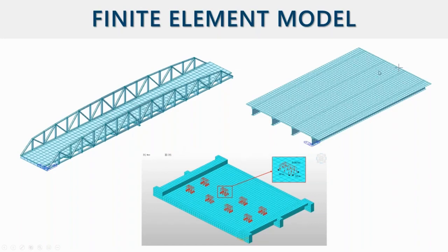This is the approach slab span with four steel beams, and this one is the approach slab span. You can notice that on the side they have these raised sidewalks, and this actually adds quite some stiffness. So we have to model this sidewalk. Also, for the applied load, we cannot apply a concentrated load. We have to consider the area, 10 by 20, the footprint of these tires.